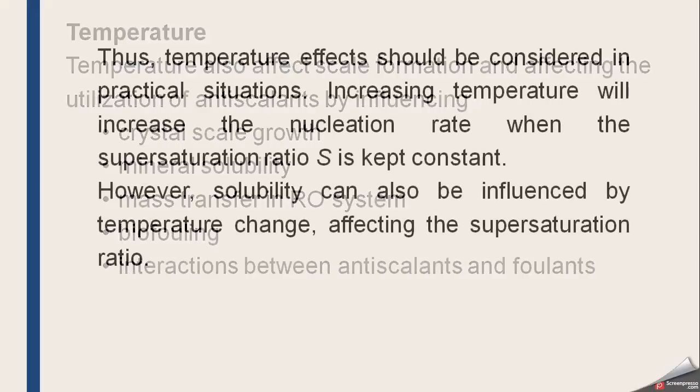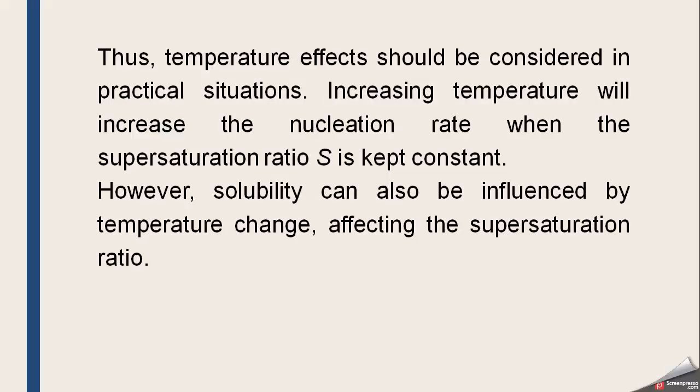For example, the temperature effect should be considered in practical situations, like increasing temperature will increase the nucleation rate, that is, more crystals will be formed when the supersaturation ratio S is kept constant. However, solubility can also be influenced by the temperature change, affecting the supersaturation ratio.